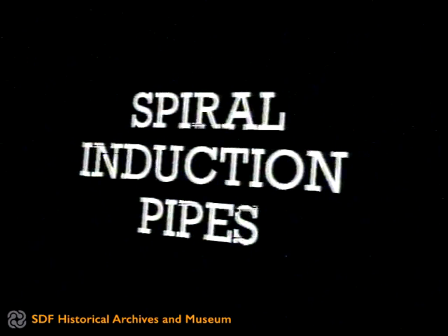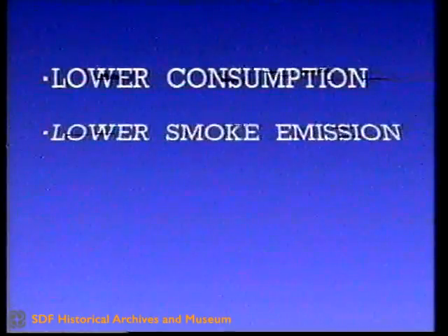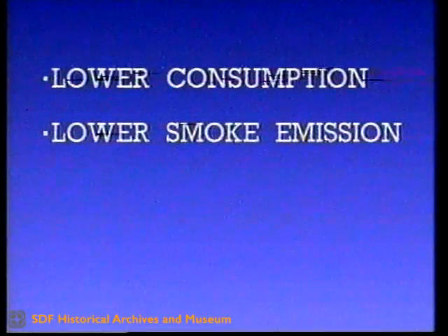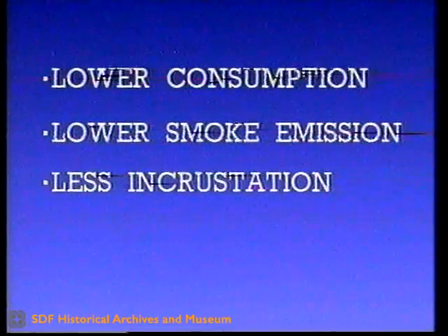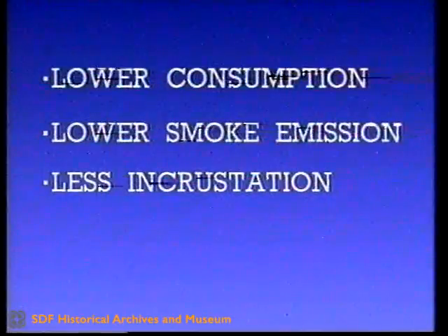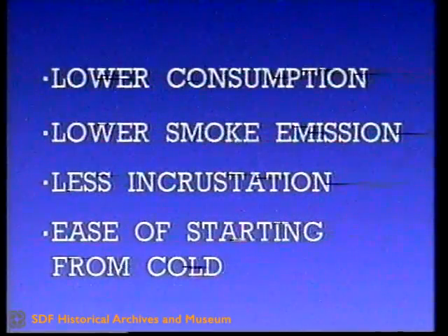Spiral induction pipes. These allow for an eddying movement to be imposed on the air on its input to the cylinder, which markedly improves the filling of the cylinders, high suction efficiency, by building up greater power, furthermore improving the mixture of air and fuel, giving lower consumption, lower smoke emission due to complete combustion, less incrustation of carbon residues, ease of starting from cold.